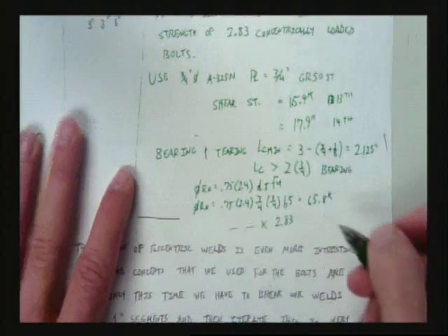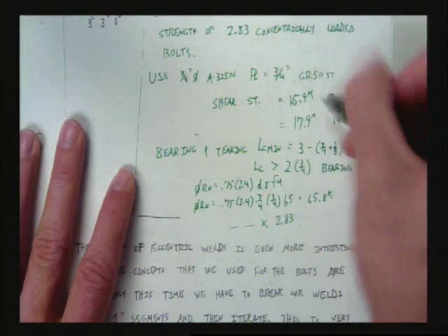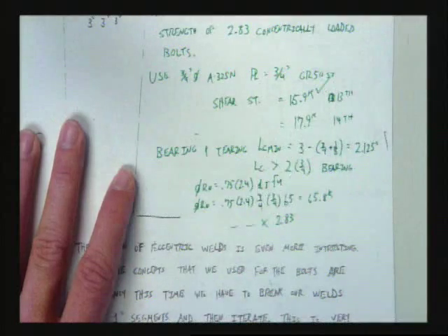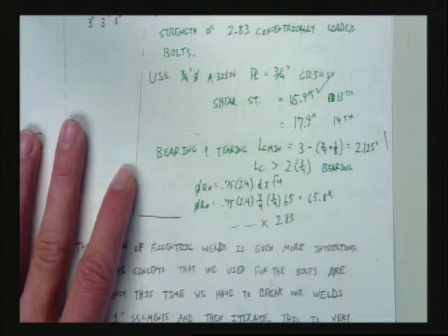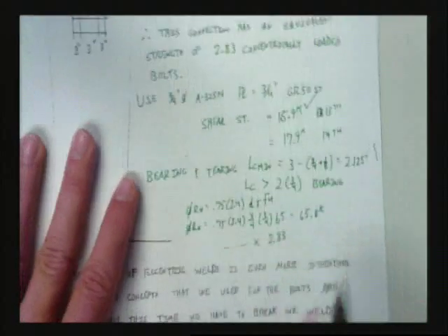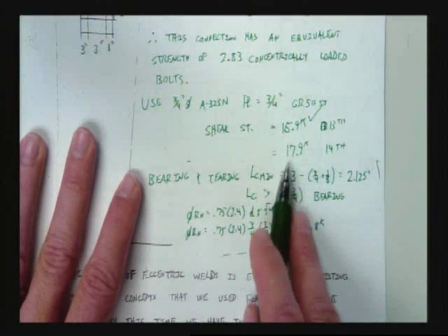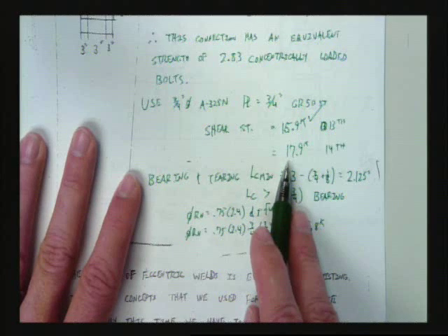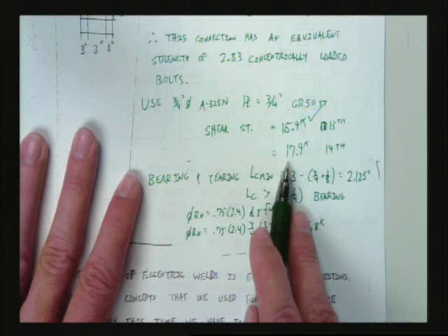Okay, so we're going to say that these control, don't they? The shear strengths are going to control, right? So, whenever you're calling out bolt strengths in this class, you better tell me which manual you're using. You better tell me if it's 13th or 14th edition. Okay?